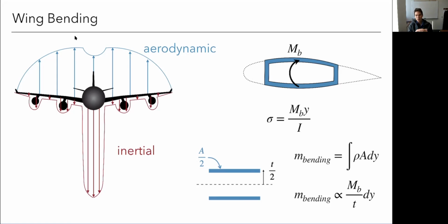Typically from a drag perspective, we'd like thin sections. Of course, there are limits, and there are some aerodynamic reasons to have a bit thicker sections, like for CL max. But generally speaking, there's a primary trade-off between thin sections, which are more aerodynamic, in other words they have less profile drag because we don't have to displace the flow as much, and thicker sections, which are generally better for structure. So this is going to be one of those trade-offs that we'll need to look at.